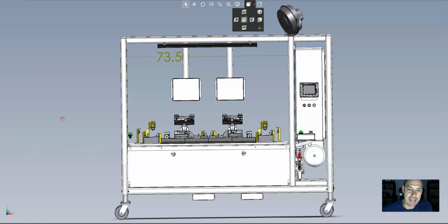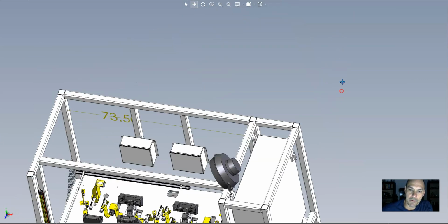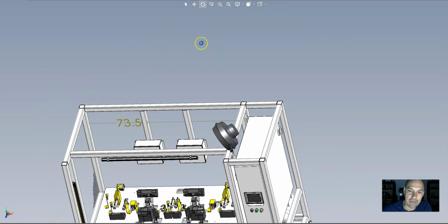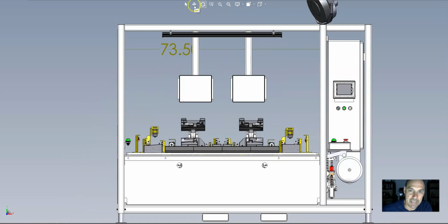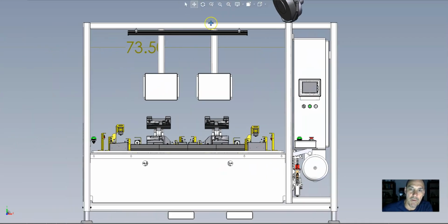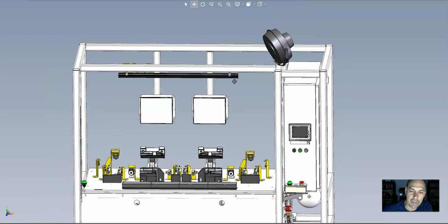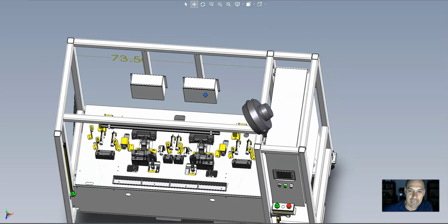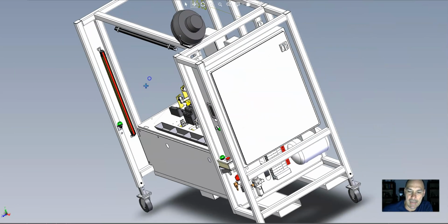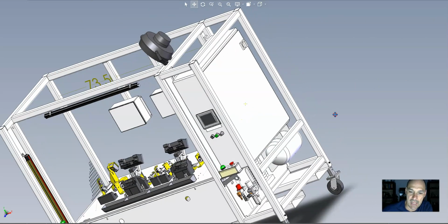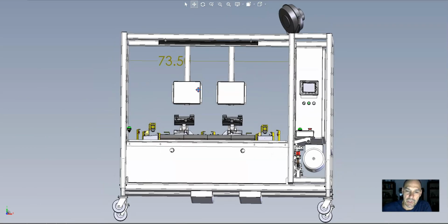This is pretty neat in the fact that I can manipulate this left and right, and I can move it around. I can look at it. I can rotate it around. There's just a lot of cool features to eDrawing. So in this particular case, I'll go ahead and pan it left and right, right? Okay, I can hit my scroll wheel and hold it and rotate it. Now you can set up your mouse to do this in a lot of different configurations, but this is what I'm doing, right? And I can look at this and pan it, and I can look at this machine every which way that I want. If it gets out of sorts too much, I'll just recenter it. Right? So this is pretty cool.